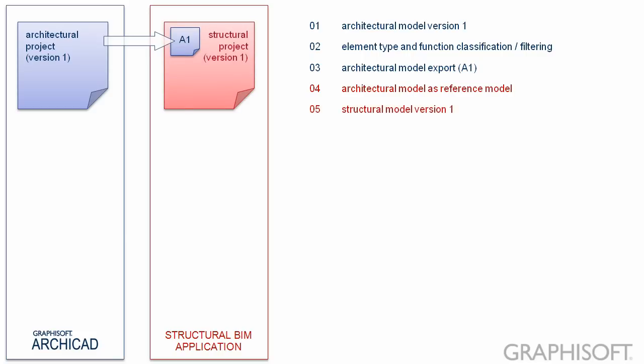5. Engineers define the structural model and its details based on the referenced architectural model. They can also generate analytical models for analysis applications. Engineers query the initial profiles and materials defined by the architects. 6. The completed structural model or its filtered part is exported back to the architects. 7. Engineers also use IFC file format for the model exchange.